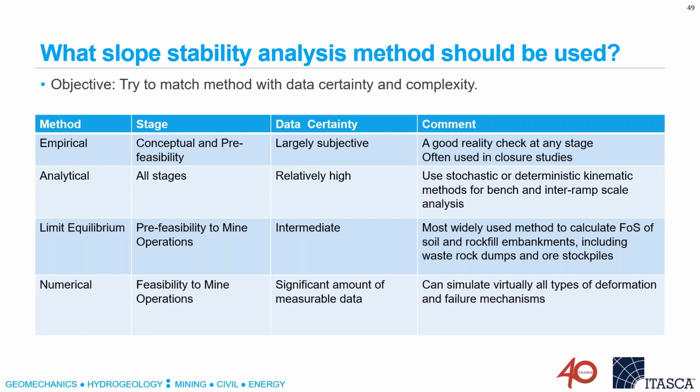Limit equilibrium methods really are still widely used, but mostly they should be used, in my opinion, for things like soil and rockfill embankments and waste rock dumps and stockpiles, because the assumptions there fit the analysis method. And then numerical methods for other types of problems.